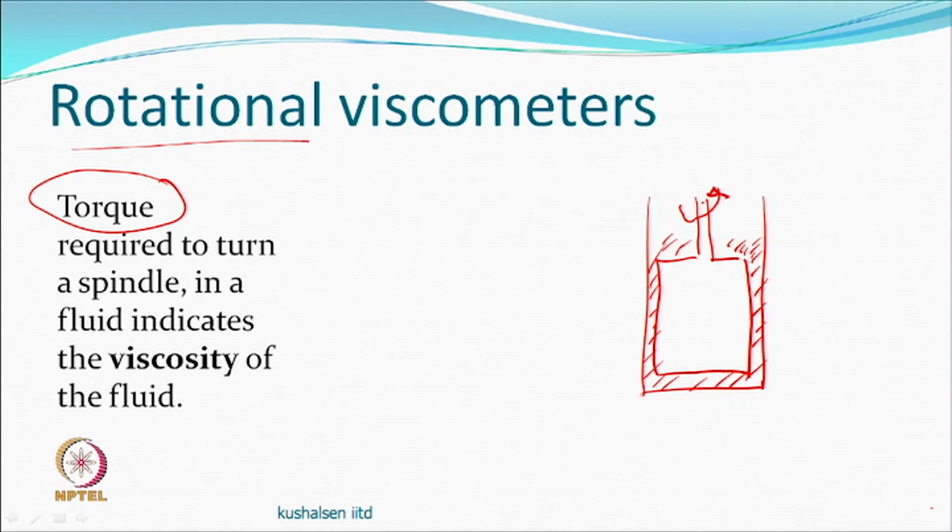That would depend on the diameter of the spindle and the diameter of the vessel in which you have put your viscous solution and want to rotate. The energy required to rotate can be related to the torque, and therefore you will get to the shear rate. Then you will also know what is the mass being rotated, what is the area or volume of this particular thing, and that can be related to viscosity.